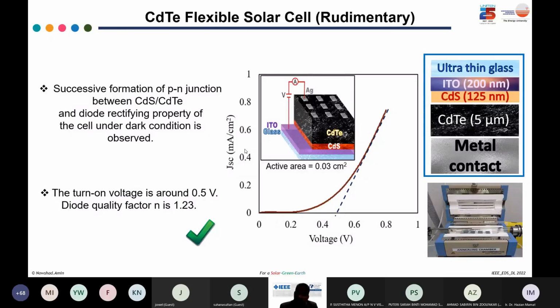Next, we are still working, but we made a stack of a PN junction and checked its photovoltaic property by dark current characteristics only. We found that it is a diode. That means it would be a solar cell as well if we really take care of the later parts, for example the back contacts or pseudo-ohmic back contacts. Then we can claim it is as good as other conventional cadmium telluride solar cells.